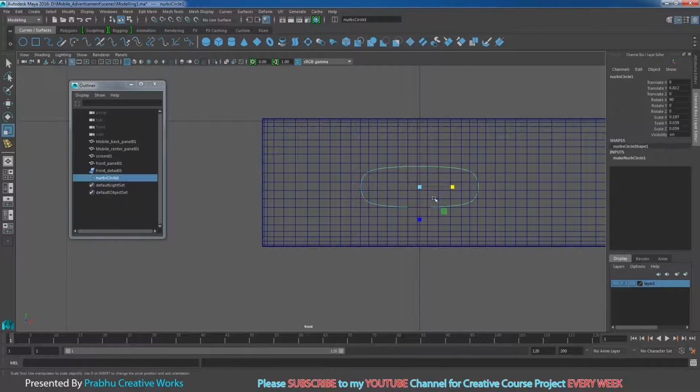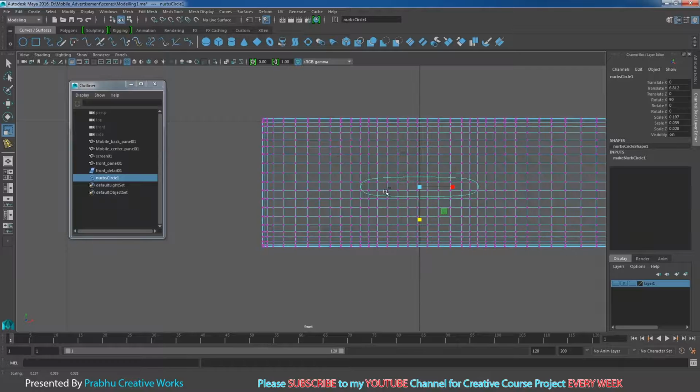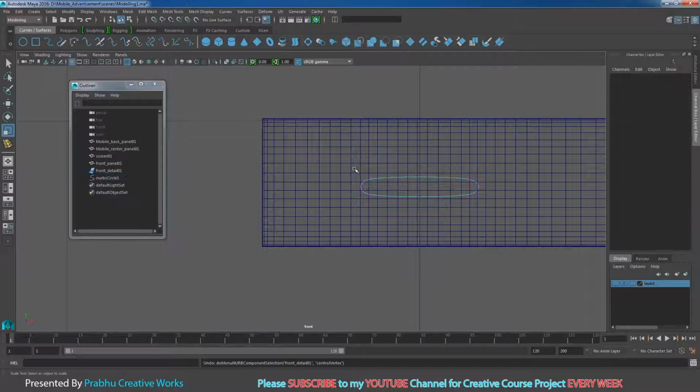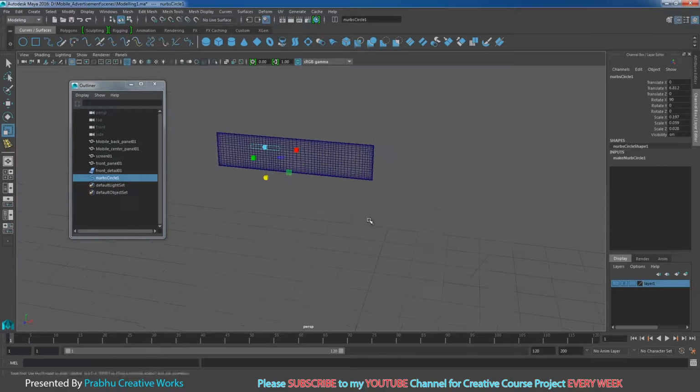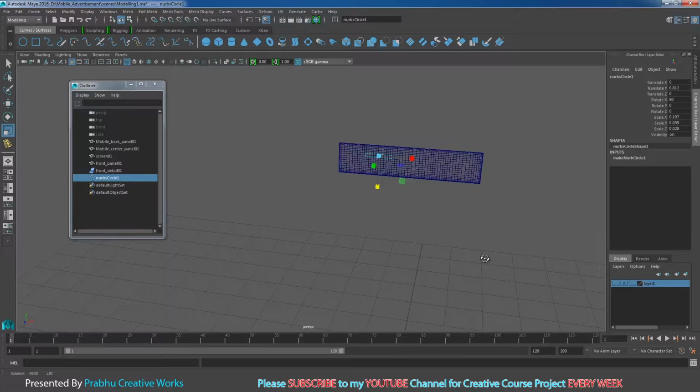Right click and choose object mode. I want to scale in Z like this. So right click and choose control vertex. I will select this control vertex, so like this. So now you want to select these 5 control vertices and scale in Z. So you want to do the same thing on the bottom side, so like this. So you want to make it extremely straight, so right click and choose object mode, go to front perspective. So I want to check whether it will be okay or not.